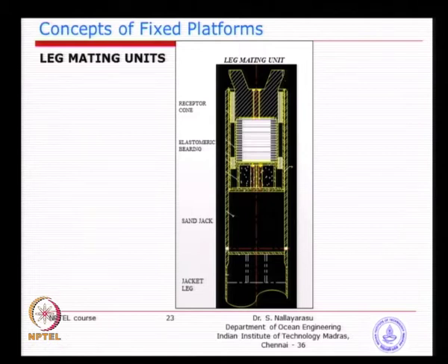You see the problem. So, the design of these elastomeric pads needs to be such that the compression is exactly what we wanted. If it is a 1000 ton reaction, you need to design in such a way that under 1000 ton it will be able to compress at least this much, so that you will be able to do the welding. Otherwise, you will not be able to make a connection with the deck.